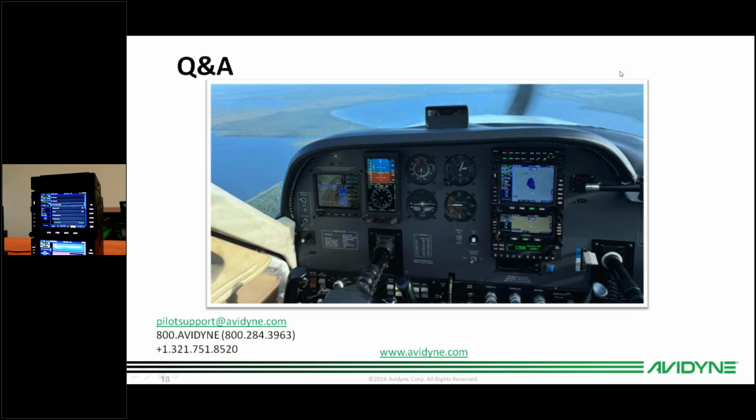If you're not connecting to the Stratus, what is the benefit of keeping open ADS-B mode on? When you're connected to the Stratus with the iPad, the open ADS-B mode allows the IFD to receive the traffic and weather from the Stratus. So if you have it set to ForeFlight mode, the IFD is not going to receive that data.